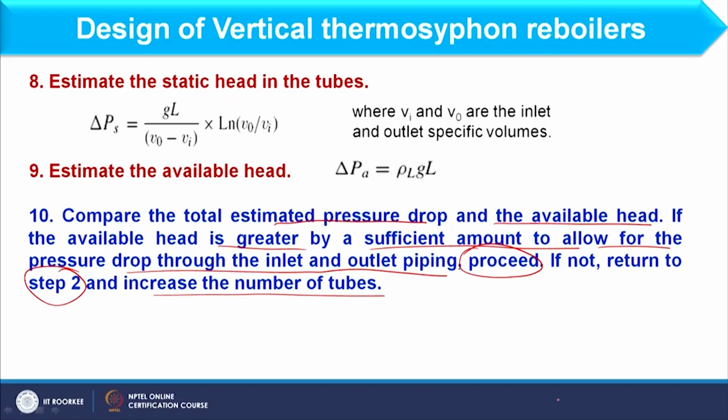In the second step, we have considered the maximum heat flux. Now, we will reduce the heat flux from the maximum value. After reducing the heat flux, when we calculate the area, it becomes larger than that available with maximum flux. So, if we fix the dimension of the tube, we can find the increased number of tubes, and whatever feed was entering the tube previously is now entering more tubes. So, it will reduce the velocity and so the frictional loss.